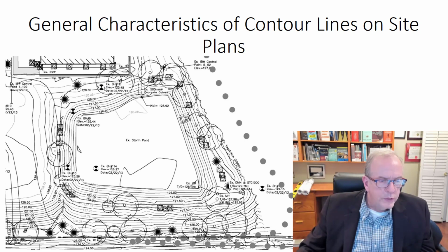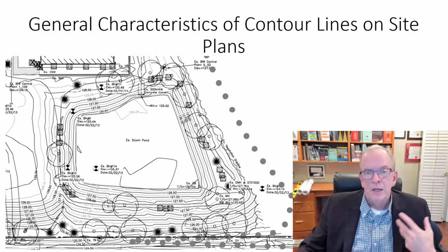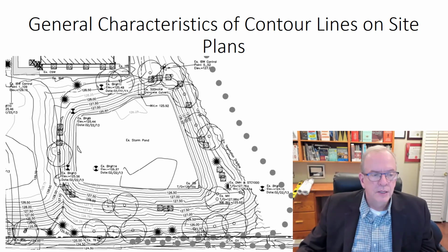And oh, these little symbols here are for boreholes. Again, if you had the legend, it would tell you that's for boreholes, and the boreholes are numbered. Essentially, the boreholes are done for geotechnical surveys and studies to reference a whole bunch of different tests that might be done on the soils in that particular area, to check the soil types, perhaps, to see if there's any toxins in the soil, if it's a brownfield site that maybe was a former factory area, or those types of things. So the boreholes can be done for a number of reasons